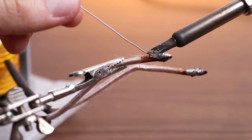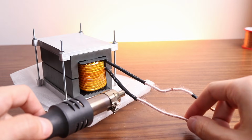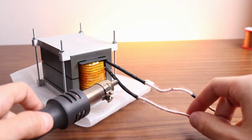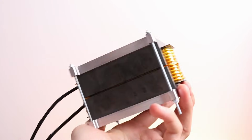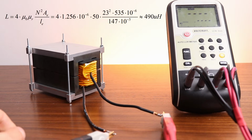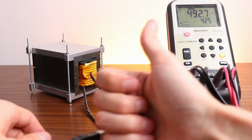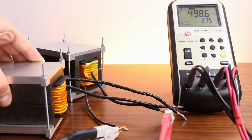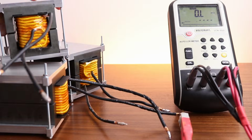A real pain in the ass, however, is tinning the Litz wire, because it has lots of strands. Each strand is insulated, so the temperature must be quite high to burn off that insulation. But anyway, did I manage to get the inductance I actually calculated? Well, it's close enough. And the nice part is that the difference between inductors is less than 1%, which is not that bad, considering the manual assembly process.